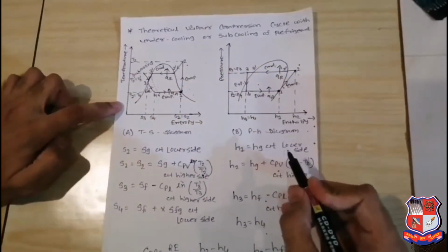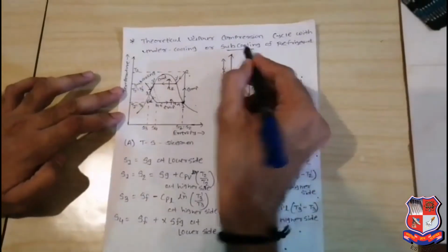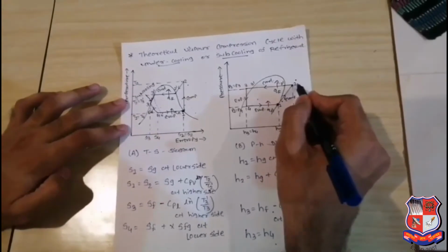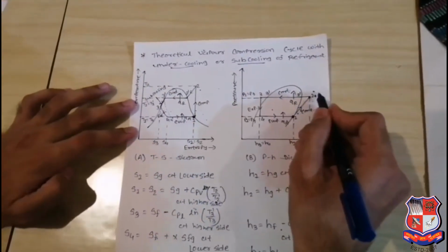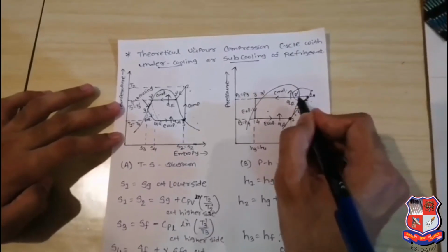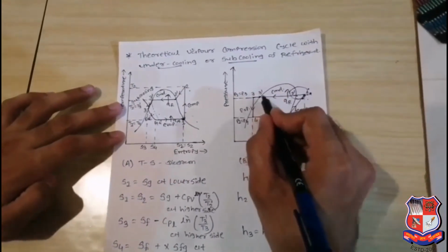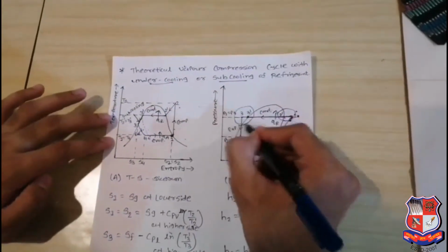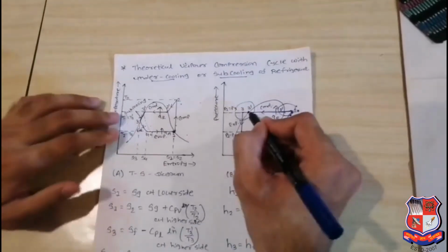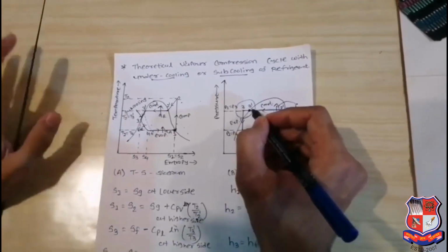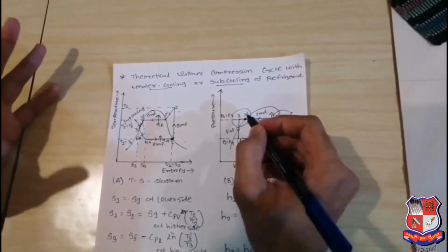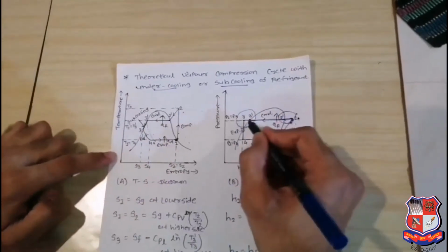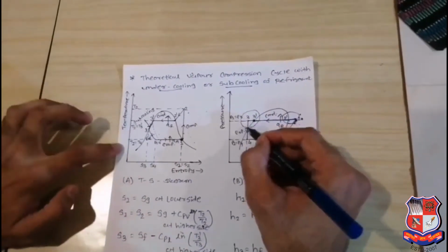Now we are going to discuss what subcooling is. I already told you the 1 to 2 process is the compression process, so the saturated vapor is converted into superheated vapor. Then after this superheating process, the vapor is converted into saturated liquid. Up to that was our previous case. Now we concentrate only on the subcooling region. Subcooling means the saturated liquid is cooled down one more time with the help of any other refrigerant or coolant, or air or water. At that time its enthalpy decreases and pressure remains constant. So that region is called the subcooling or undercooling region.